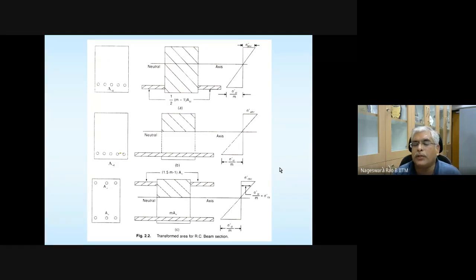So if this is a rectangular section beam subjected to hogging moment, top fibers are going to be in compression, bottom fibers are going to be in tension. Even for the top fibers in compression, if you want to reduce some load on the concrete, some steel can be provided in the top layer where compression stresses are more. So that is this kind of beam.